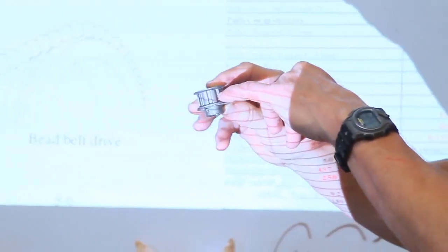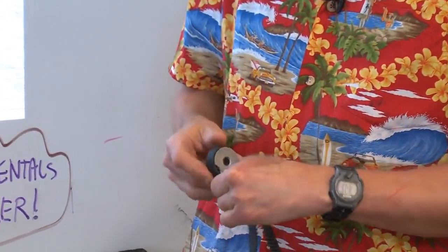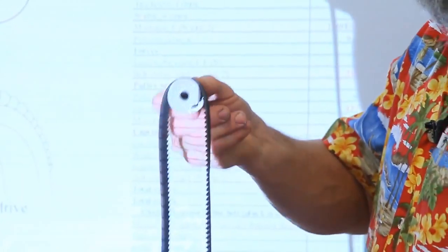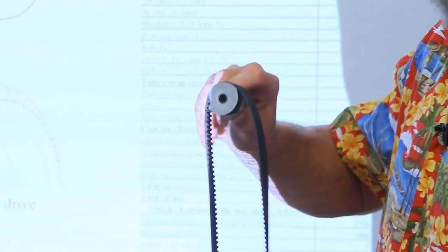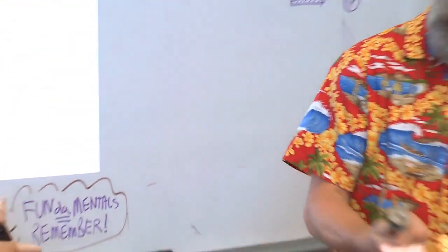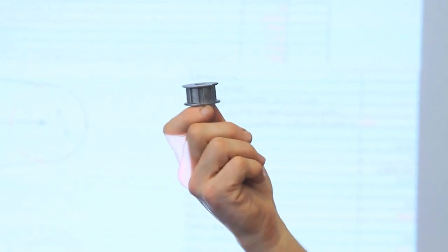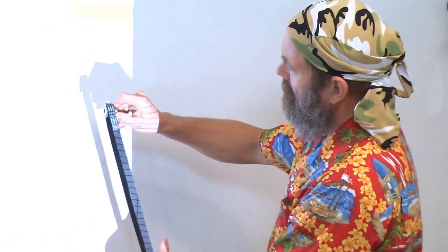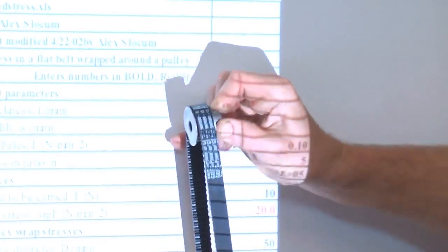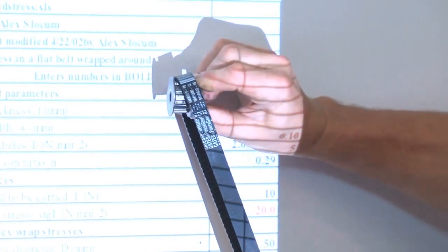So you see I've got this timing belt pulley here, or a sheave sometimes called, and it's got teeth in it. And I just happen to have an extra timing belt here where the teeth engage, and so you don't need a whole lot of tension in order to transmit torque. What are these rims on here for? And what would happen if I had my hand as the motor and I'm trying to transmit? See, I can transmit torque here, but if I'm misaligned, things can come off.